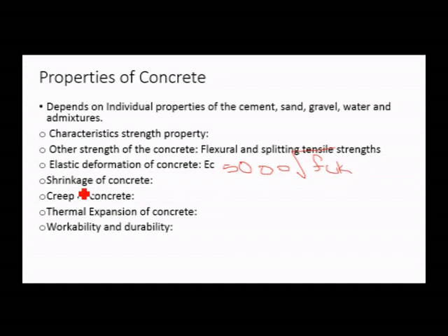Shrinkage of concrete should be considered, a time dependent deformation, generally compressive in nature. The constituents of the concrete, size of member and environmental conditions are the factors on which the total shrinkage depends.